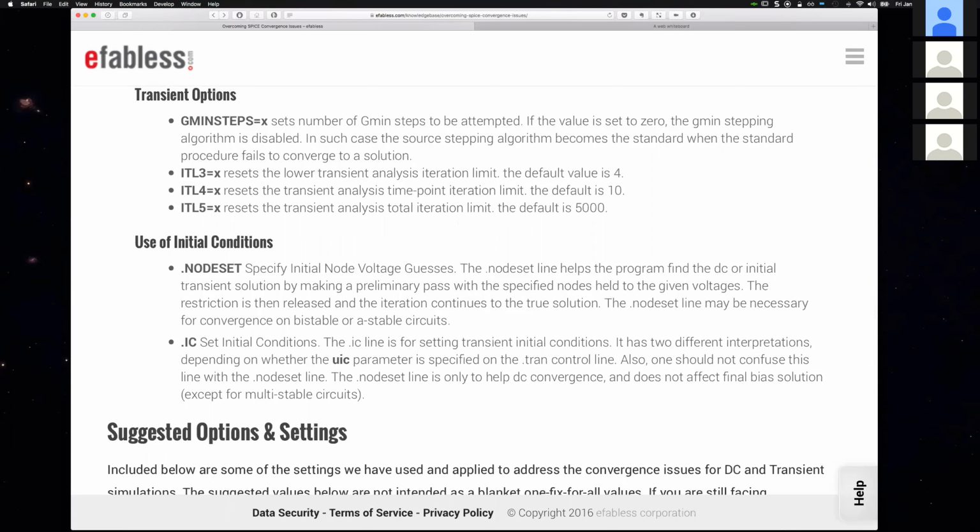And in the transient analysis, you can use the initial conditions. Usually in the transient analysis, you add UIC. There are examples of that in the manual. Once you enable that, it goes in combination with the .IC, which is the initial conditions, node by node. If you leave it by default, it gets set to 0, and it puts the circuit in a different state, so that you can see the results, and it helps you either converge or get the right results.